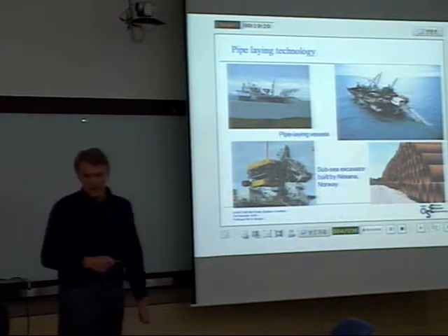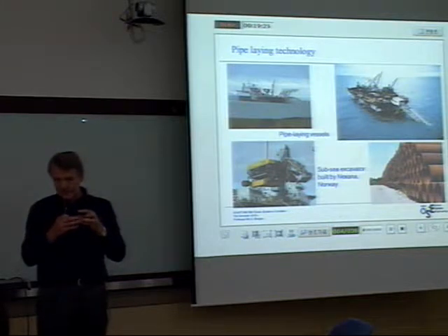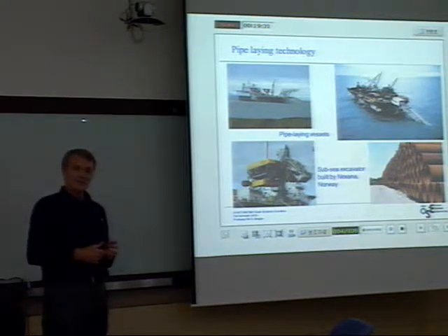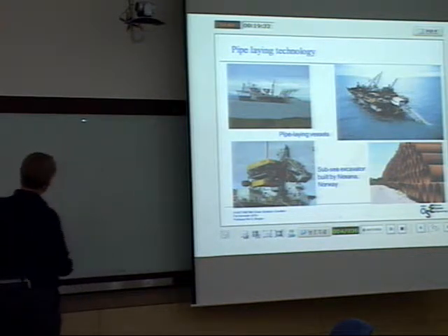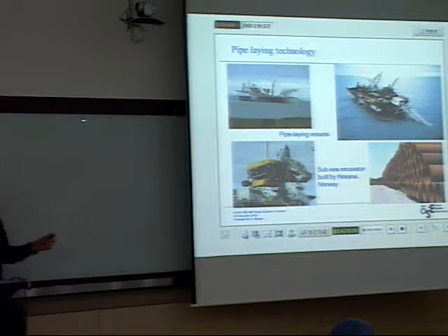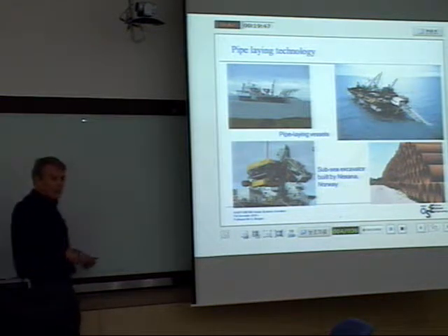This is high strength steel, but of course it has to be weldable steel, right? Well, it's pretty stiff, but of course, when you have such tremendous lengths, it bends, you know. But if you lose the pressure, the pulling force here, it will buckle. It will buckle, and there's even something called a propagating buckle.